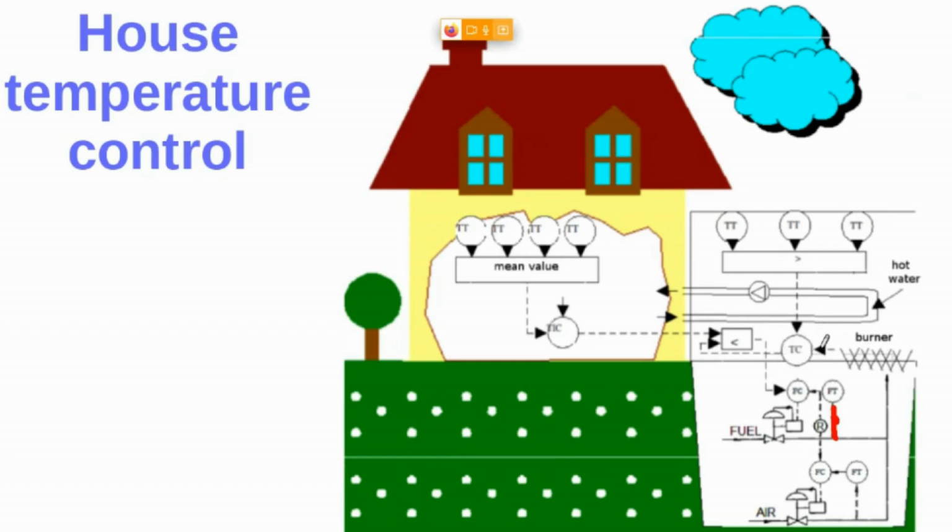So this is the set point in here. Here we have the set point, and this must be the process variable. But as you can see here, the process variable is obtained thanks to a selection criterion applied on several transmitters. So here we have a selective control structure because this selection is applied not on manipulated variables, because in this case we would have an override control structure. We have, in this case, a selection control structure, just because we are selecting among these transmitter values, right?